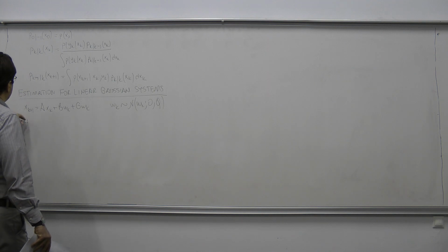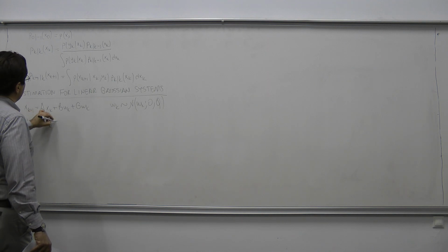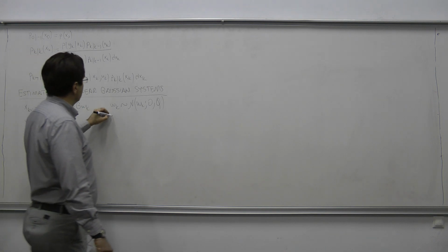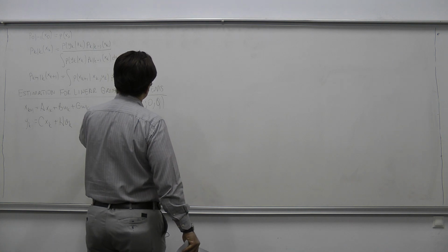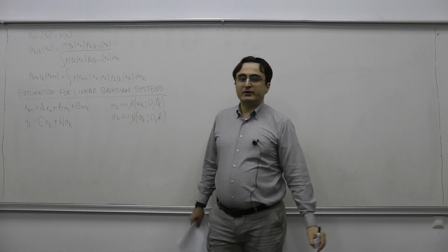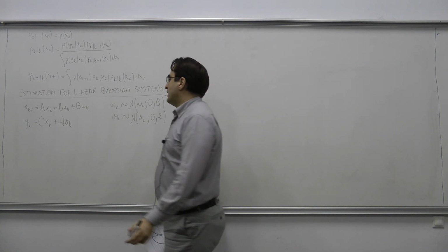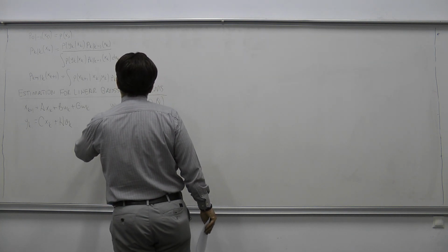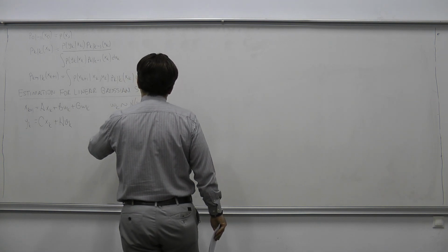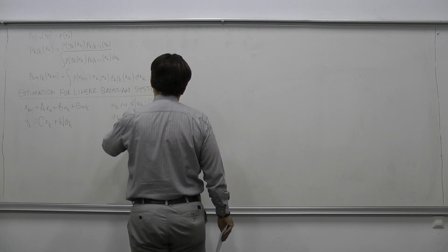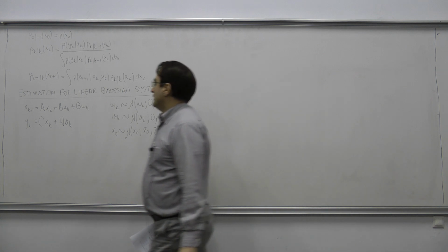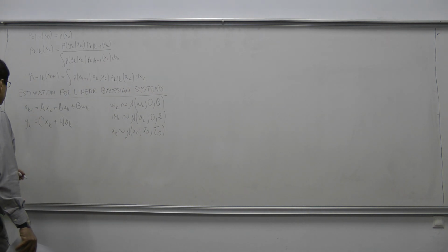And I would have yk is equal to C xk plus H vk. And vk is my measurement noise. It's normal with zero mean and covariance R. And also I need to define here what x0 is. x0 is random, which is normal distributed, with mean x0 bar and covariance sigma 0. Okay? And then I need to talk about the input.